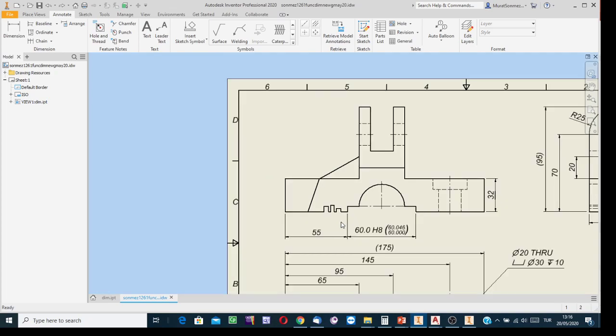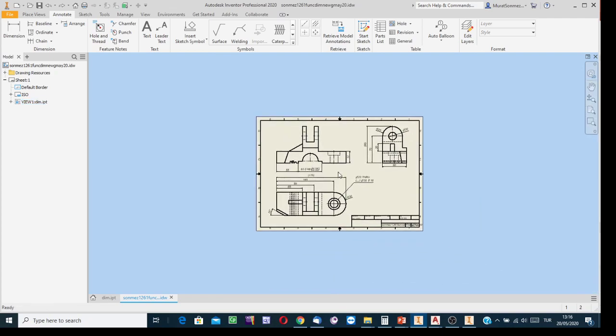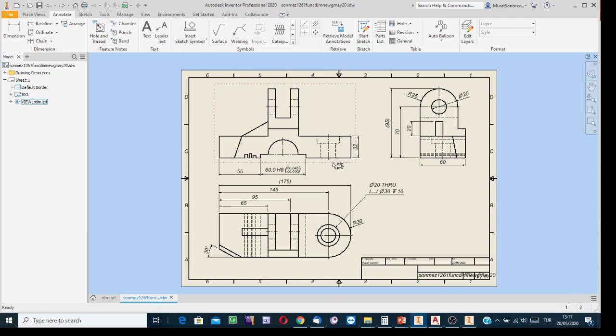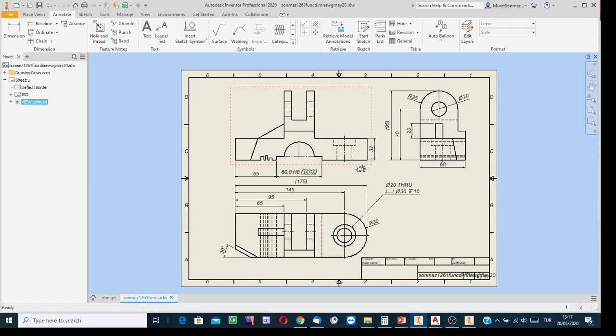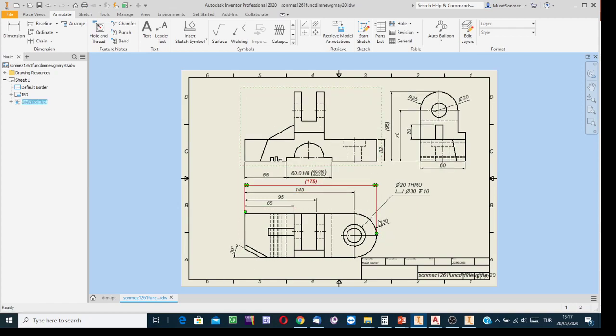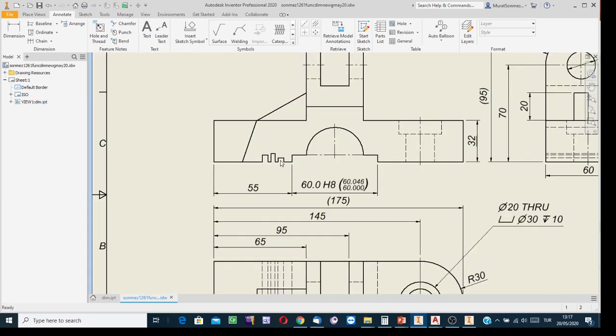You know, if there are tiny parts, and under the selected scale factor the image of the tiny part is not so distinguishable, and also the space is not sufficient for the numbers and for the termination symbols when showing the dimensions, a detail view is recommended. Now, the best solution for such a case is a detail view. I think I can slide this view here to have empty space. Using this empty space, I'm going to create a detail view for this part.